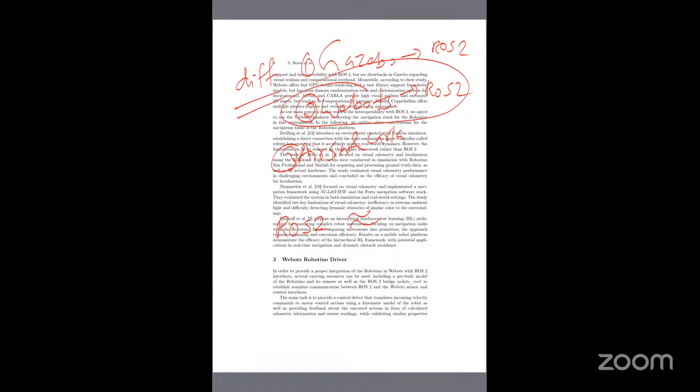This driver will collect information from ROS2, for example command velocity, and it will be converted into the 3 omni wheels motor commands. Wheel encoder, IMU, LiDAR, all these sensor information is published as ROS topics and used to calculate the odometry.